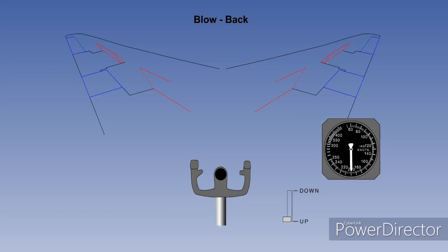There are no speed restrictions for the operation of speed brakes. However, the design of the hydraulic operating system does give a blowback facility. That is, for the same selection from the flight deck, increasing IAS restricts the speed brake angle of deflection into the airflow. This prevents excessive buffeting at higher IAS.